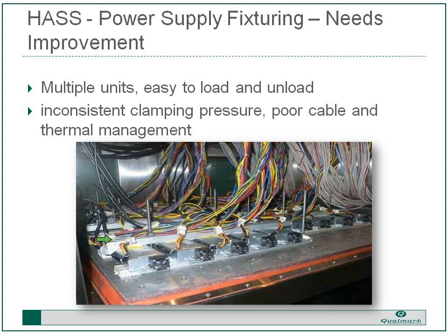Now, if you've done this before, you probably will realize almost immediately that there's going to be a bow in this bar. You'll get clamping force on this corner and this corner, and the rest of them will not see that same clamping force. Indeed, with a setup like this, you might even see the ones in the middle starting to move out.